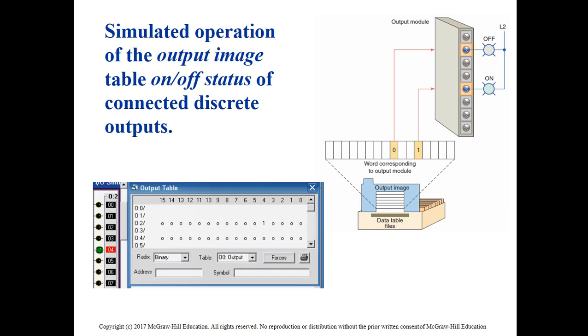So you can see here we have one output at number 4. You can check that the status of number 4 is 1 here, 0 to 1. So the status of the output inside the output table will change from 0 to 1 based on the command received from the CPU module. So we call this the output table, or input table.